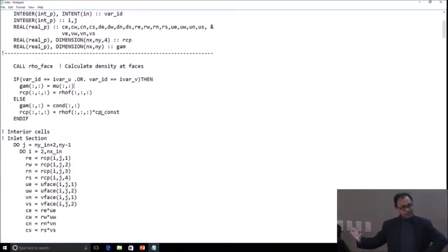It's the same link coefficient routine, which is calculating the links for both the energy equation and the momentum equation. In one case, it is setting gamma equal to mu and the density equal to density, basically. And in the other case, it's replacing density by density times specific heat capacity and gamma by thermal conductivity. So that's just a top level decision.